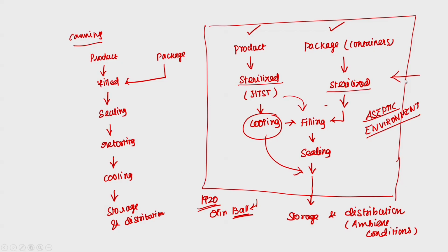This is a small introduction. And one more thing we need to consider here is the HTST processing. Most of the product here is liquid or liquid with particulates. That means we are going to handle only fluids, and the important thing is we need to better understand fluid characteristics as well as the heat transfer phenomena along with fluid flow to design a proper system for aseptic processing, right. That is why the process is an HTST process here.